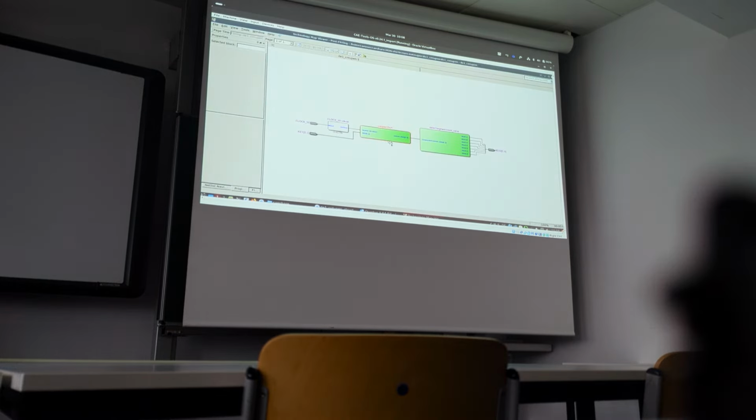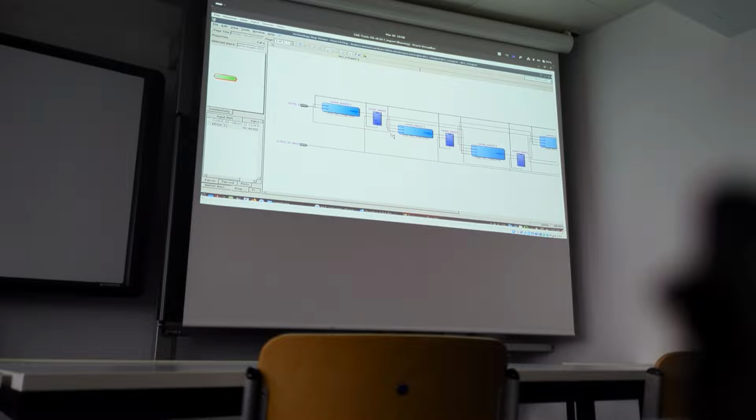Very similar to the RTL viewer, but now you can see it introduced a special element, which is a clock control driver already on the chip. Lots of clock control drivers are available, and we have dedicated input pins to connect to that. The designers of the prototype environment used that. And again, we can go one step below inside the counter.